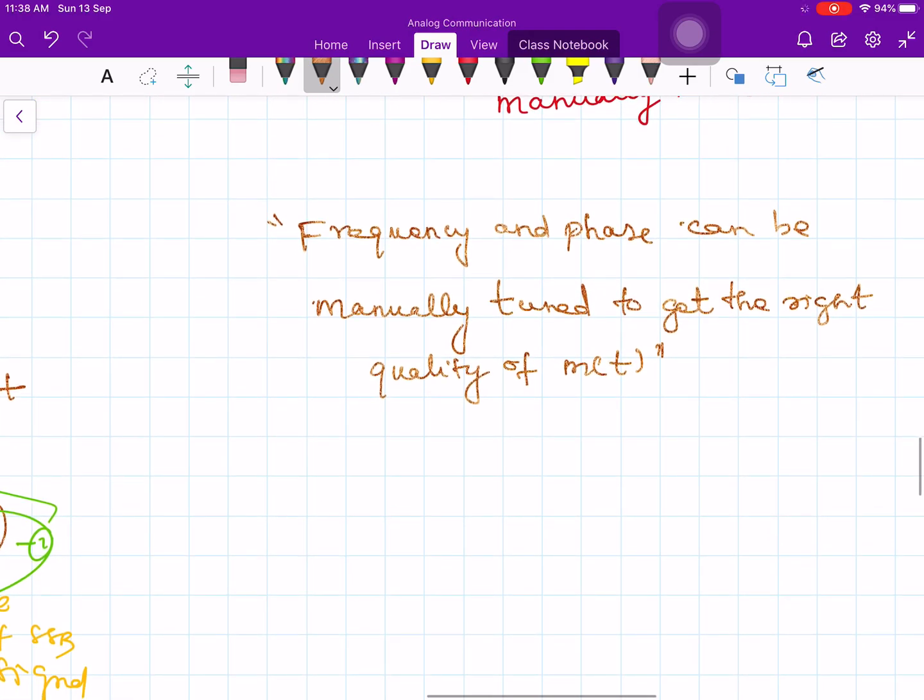Okay, so that's about single sideband modulation. Single sideband modulation is good if you want to save the bandwidth. It is a little more tricky to demodulate, like we have just seen. But these complexities one ignores if bandwidth is a very major concern to us. We will try to do whatever is required to make the carrier work very well. If the receiver becomes very complex in the process, we don't mind, because bandwidth is important. It is an important resource for us.